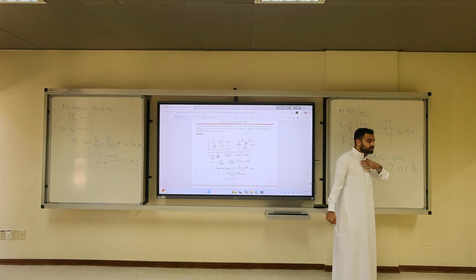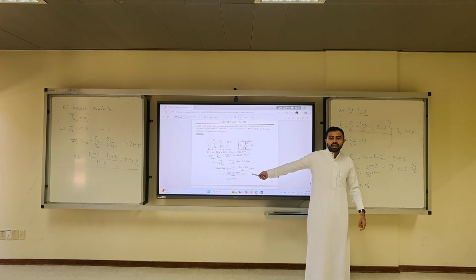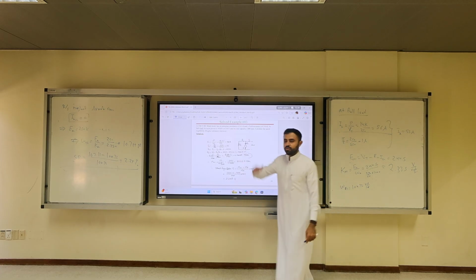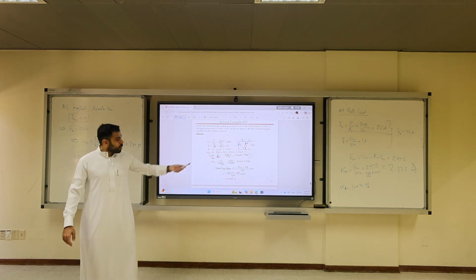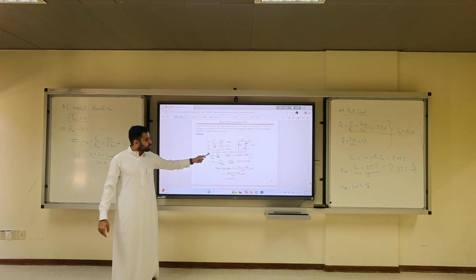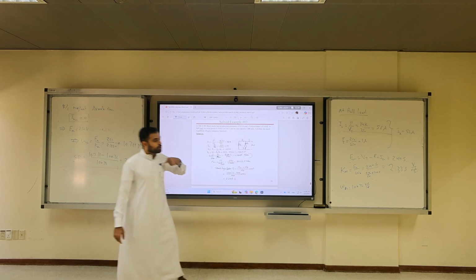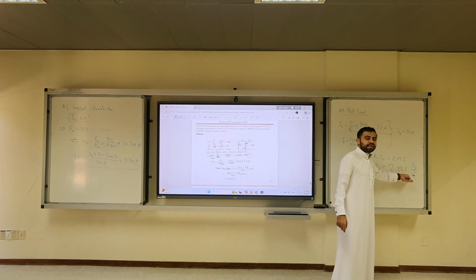But what is the cost? I had to convert the 1000 to RPM. Here he didn't, and he got the final answer in RPM, because he is asking for the speed regulation, which is unitless. It doesn't matter if you do omegas. But the key here is we have two different constants. One constant as a function of voltage over RPM, and the constant I did, the same as we do in class, as a function of V over radians per second.